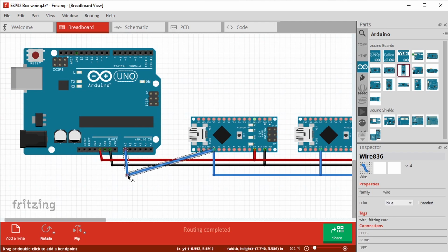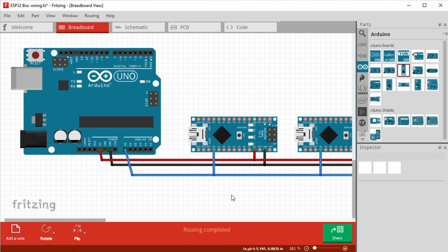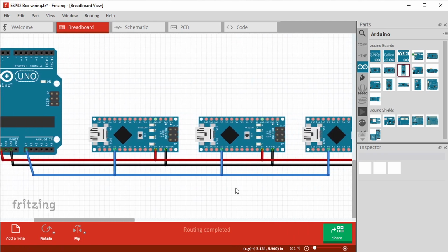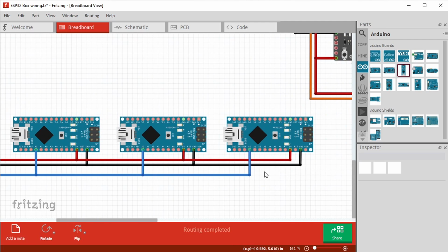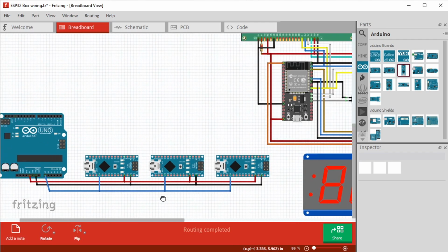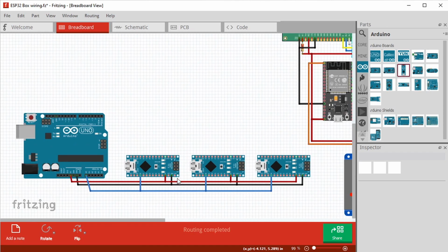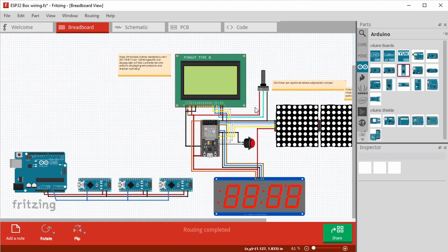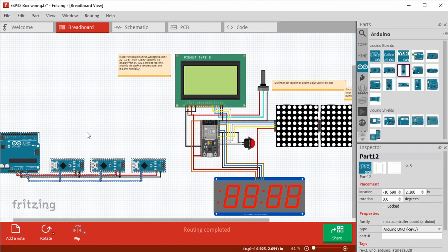So I'm going to literally double check by looking at the devices in front of me, and then by looking at the pins that I've drawn here too. So I've got 5 volt, ground, A0, yes, 5 volt, ground, A0, 5 volt, ground, A0, 5 volt, ground. Okay, so that is a faithful reproduction of the hardware which I got to work using the most basic example of the PJON network. So pressing a button here caused it to be received by all 3 slave devices, and pressing any button on the slave sent a message that was received by the master. So what I now want to do is I've got these 2 separate bits of functionality at the moment.